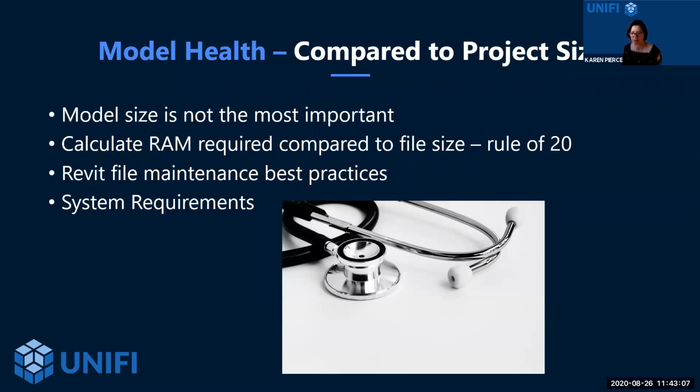I've done it with mixed results, but when I did it and I enforced it, what I really found is that when I'm able to periodically open the model and audit it, I can then purge unused, I can review warnings, but really what I'll do then is also audit it and compact it. And I'll compact it under a new name, and I'll do that twice. And then I'll essentially rename it back to its original file name. So when I'm able to do that, the performance is a night and day difference.